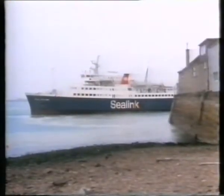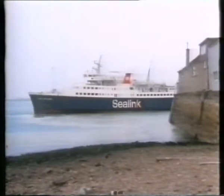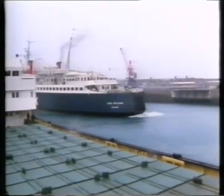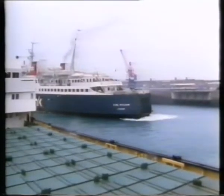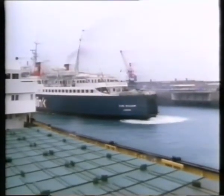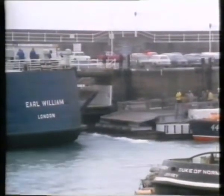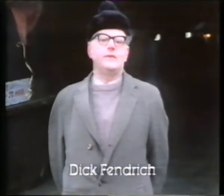This ship has a problem, and it's not a very unusual problem either. It's shared by quite a number of ships. The problem is one of low-frequency vibrations caused by some cyclic force. Now, in this case, the cyclic force comes from the action of the propellers. It may be, in cases like this, that the cyclic force causes resonance, or at least uncomfortably large vibrations, in some part of the structure of the ship. In this case, the trouble is on the floor of the car deck.